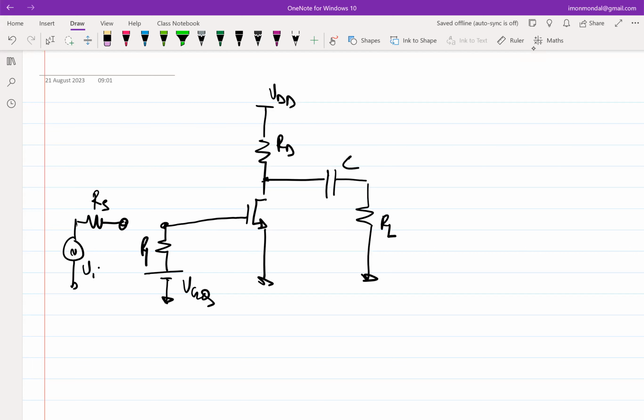The moot point here is that we'll have to derive the voltage at the gate junction from a higher power supply, that is generally VDD. Okay, so the highest power supply in the chip. So you will have to use that to bias all the transistors. If you have 100 transistors, 100 amplifiers or 10 amplifiers, everything has to be derived from that particular power supply. Okay, so let's assume that for certain power supply, you require 2 volts.